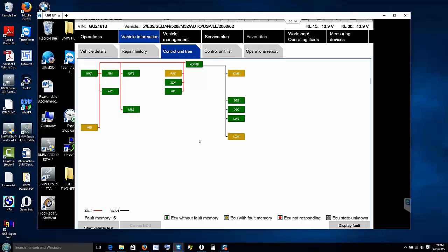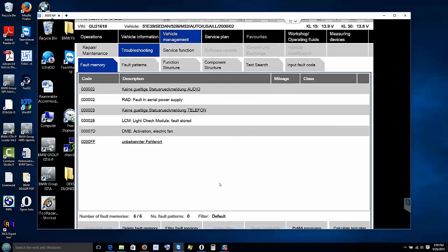All right. Everything is green now on the DSC. The fault code is gone. What do you want to check out on this car now? Well, I was just looking at it, and these rear lights are on, showing that the bulbs are blown, but you have aftermarket lights in it. Okay, so in the cluster there is a light on to say that the bulb in the back is blown, right? Yeah, it's showing the two bulbs in the back blown.